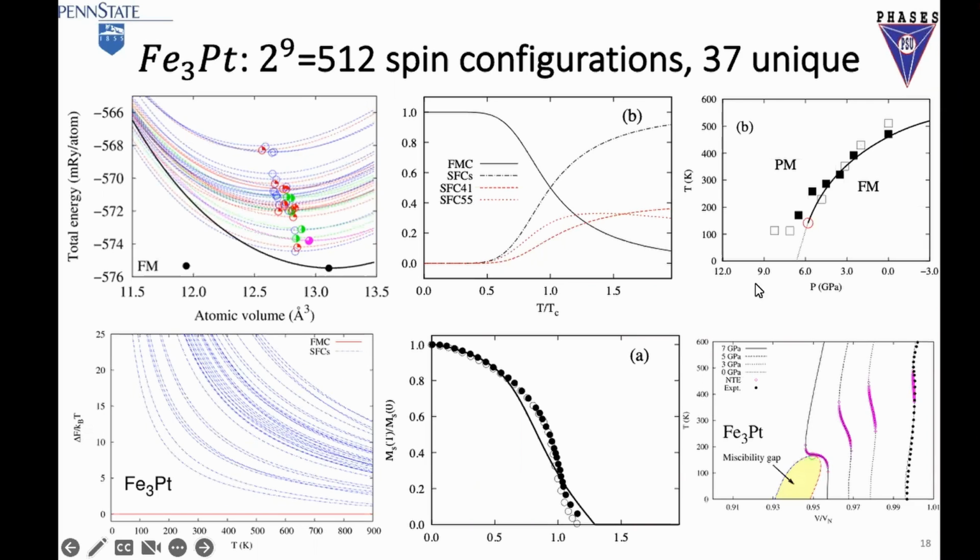And then, if you change the pressure to volume, you get this blue range here, which is negative thermal expansion. The purple lines are for different pressures. You put them together, and you see there's a band here where you get negative thermal expansion. The reason is that those metastable states have volumes smaller than your ground state. Even though each of them has positive thermal expansion, when put together, the macroscopic volume can decrease at a certain pressure and temperature range.